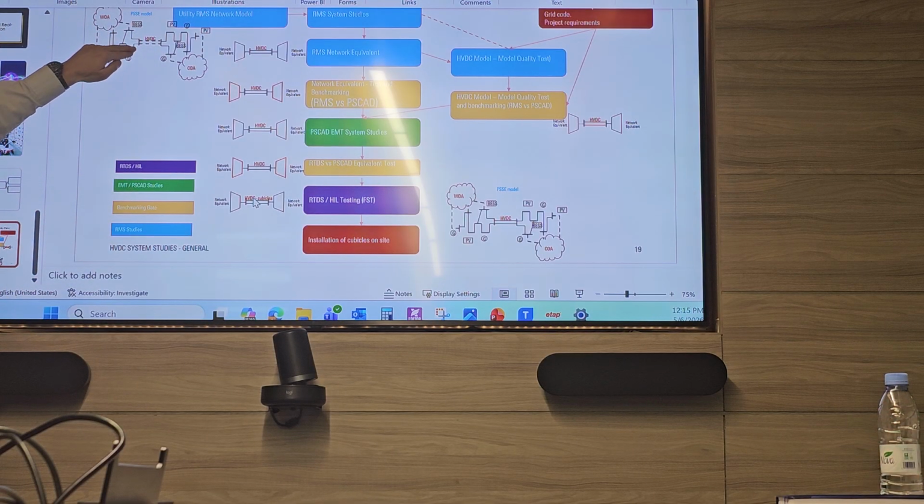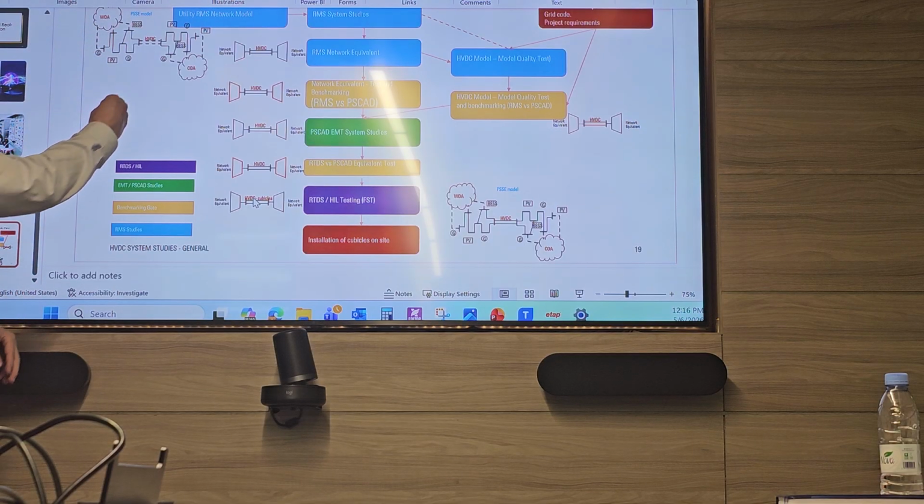And now, if you have no grid forming, you cannot do much. You're supposed to wait for this generator to connect, to bring voltage here, then you can connect to the network. Then with grid forming, you do not need to wait for this generator. You can start forming here, so you can energize here, maybe provide some load for something, then this generator can synchronize with you, so you're able to control, command.